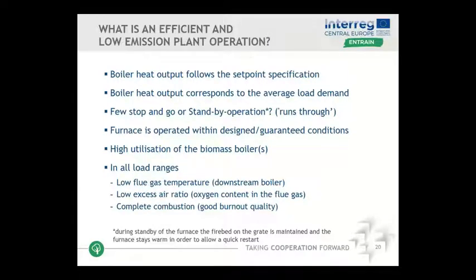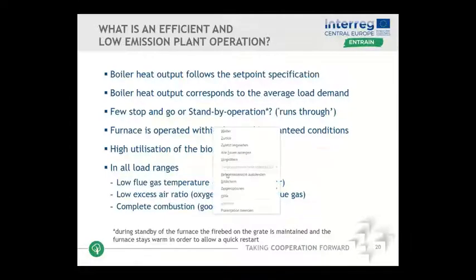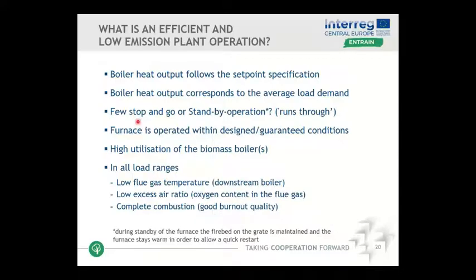What is an efficient low emission plant operation? I have pointed out a few things here. The most important thing is hidden in here. I'm changing to the laser pointer. The furnace has to be operated within designed and guaranteed conditions. That's very important. If you're outside of these operating conditions, we will have bad combustion conditions. This causes a lot of emissions. This causes a lot of other problems within the whole plant.